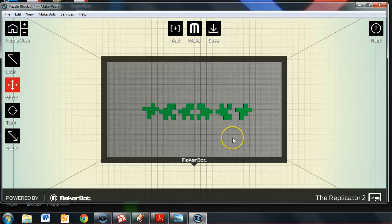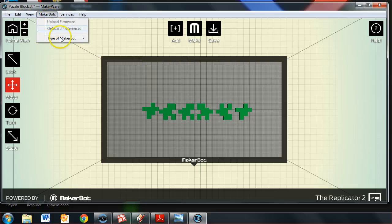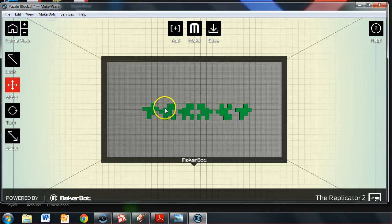So, print settings. As you can tell, I'm printing for the Replicator 2. That's what it says down here at the bottom of the screen. If you have a Replicator 2X, it's important at this time to make sure that you have the correct MakerBot, or the correct 3D printer, selected. So you go up to the MakerBots drop down, and then select the type of MakerBot that you are currently working with. So I'm using the Replicator 2. That eliminates a lot of other options that I would need. For example, with the Replicator 2X, you can print in dual colors, but at this time I only have one model on here, so I can only print in one color anyways.